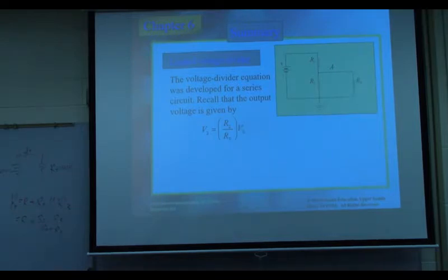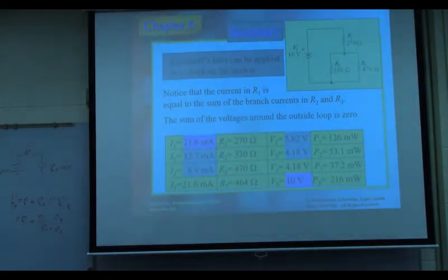Okay, let me give you a hint. Go back to one slide. Look at this one. This one looks like a loaded voltage divider, right? Exactly the same. What I want is the voltage on R2, which is the same as on R3. So combine R2 and R3. In this table, we calculate the total current first, then we calculate this voltage drop, then we use KVL to calculate this one. So it's Vs minus V1 in this case.